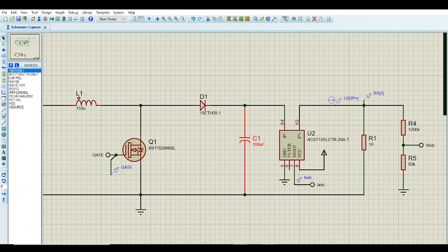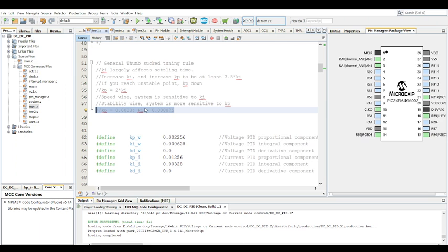So just try to, with your capacitor value here, limit it to 100 microfarads. I know some topologies require you to go to the thousands. That's a special case. If it is indeed that case, then I'm sorry. You have to start very low here with your Kp and your Ki values. But